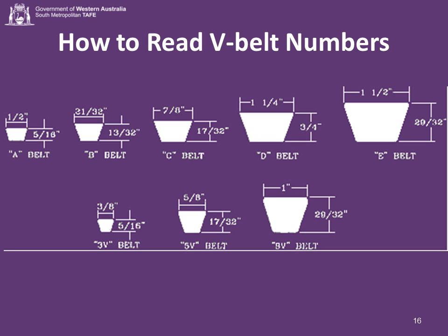In contrast, classic V-belt numbers start with a letter identifying the cross-section, A through E. A series belts are the most common. The number following is the inside length in inches. The outside length is typically 2 inches, 50 millimeters, more. An example would be A44. This is 44 inches long on the inside, 46 inches on the outside. In other words, it's equivalent to the 4L460.